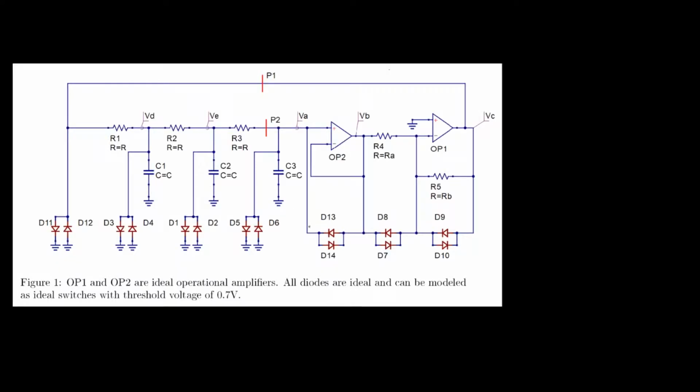We can already eliminate some options by looking at the answer from question 24. In that question we found that D13 and D14 will never activate. Moreover, we found that D7 and D8 will cause this oscillator to become unstable, so that cannot be the correct answer. We also learned that the diode pairs D9, D10 and D11, D12 will activate at the same time, so these might be an option.